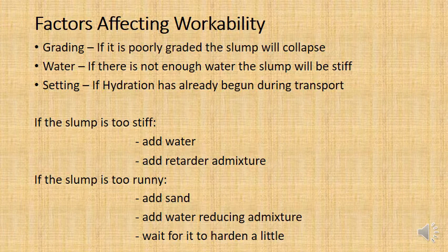So if we're adding excess water, that water will eventually evaporate when the concrete dries, and that's going to leave voids inside the concrete, which will make the concrete weaker.